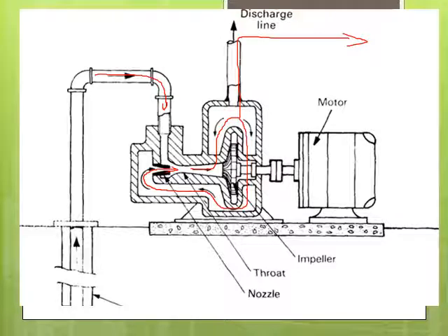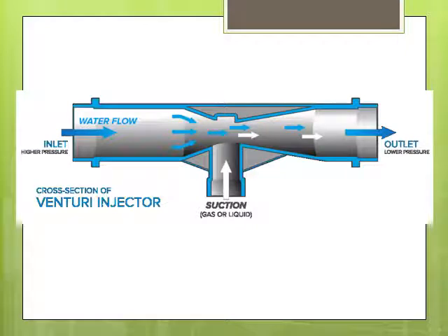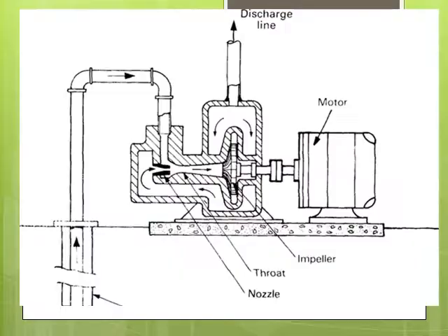This jet part where the water shoots through this narrowing nozzle through here helps suck the water from the pond. That's why it's called a jet pump. This added velocity draws the water in. We call that a venturi. Here's a cross section of a venturi. So if I shoot water through here where the passage narrows, see how it gets narrow here? The speed, the velocity increases, which creates negative pressure, and that pulls the water up. So jet pumps are suitable for higher lifts. So we have to lift the water more than 15 feet below where you are. Okay.